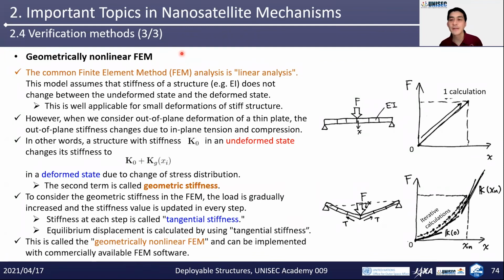Another method in numerical analysis is called the geometrically nonlinear finite element method. The common finite element method, FEM analysis, is linear analysis. The linear analysis model assumes that the stiffness of the structure, such as bending stiffness, does not change between an undeformed state and a deformed state. This is well applicable for small deformations of stiff structures.